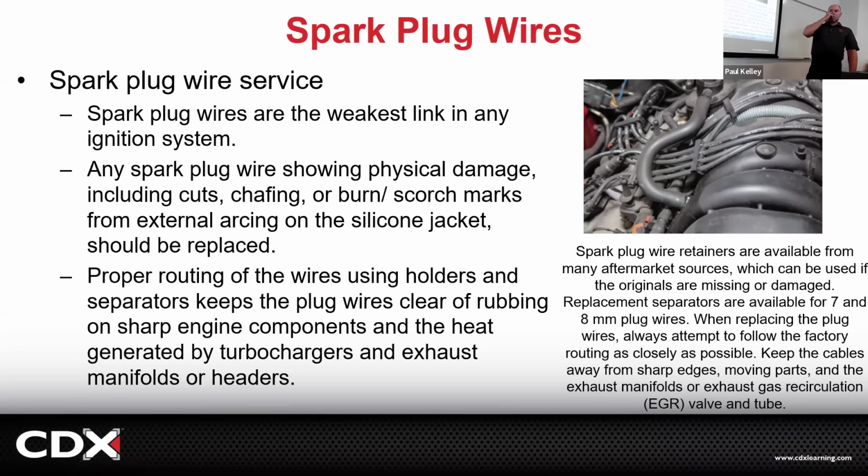All right. So who has ever taken their car through the car wash, washed under the hood, and afterwards it wouldn't start? Mason, is that true? All right. If it's an old car, I can tell you most of the reason why. Remember how water is a decent conductor, right?